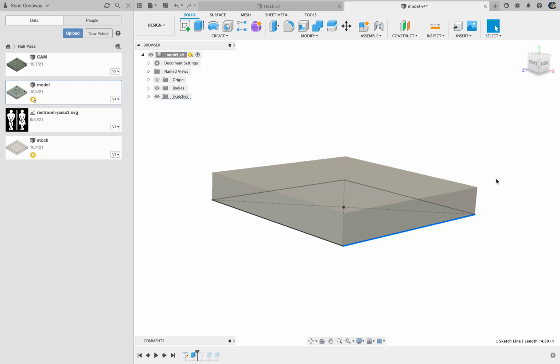And you can see, if I click on this edge so you can see how tall the extrusion was, it's 0.65 inches. Remember, my stock is 0.75 inches. So we know for sure that my machine is going to go and carve away 1/10 of an inch of my stock. All right, and then here's the next step that I took, okay?